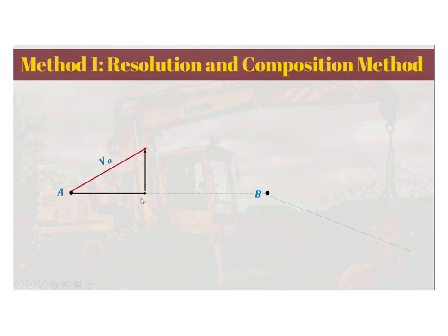Now, it is also said there that you can equate that the velocities along the line are equal since they are on the same line. We can say that along this line here, AB, the component of the velocity of B is equal to the component of the velocity of A. Thus, we transfer this line to point B. We call that line EA. We will transfer that to B. So this line now is equal to the line EA. So they are of equal magnitude.